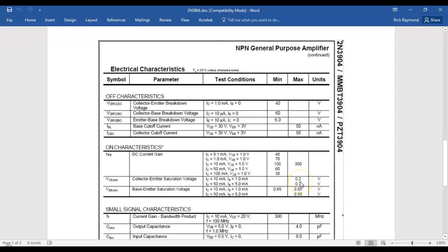So a transistor, if you measure 0 volts across a transistor, it is bad. Because it's got to drop something. It's not a closed switch, right? So we got some troubleshooting that we'll look at, and it'll show 2 voltage measurements. One's on the collector, one's on the emitter. There's a sign. So odds are the transistor is shorted.